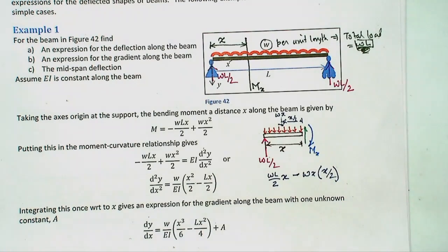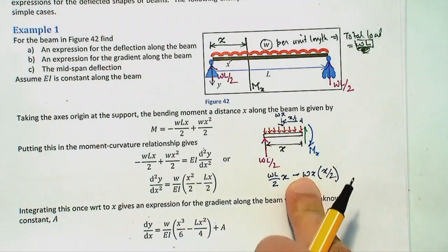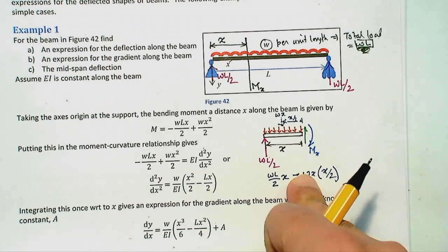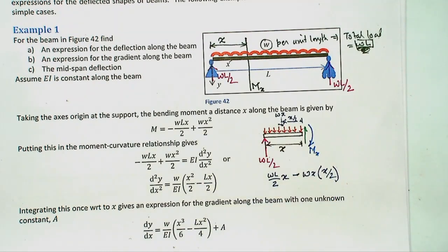As I say repeatedly, for this equilibrium equation you need to choose whether you will take clockwise moment positive or anti-clockwise moment positive. It doesn't matter which, but when it comes to the beam, the pair of left hand side and right hand side makes the sign convention. So if one side is clockwise, the other side has to be anti-clockwise. Same with the shear force.